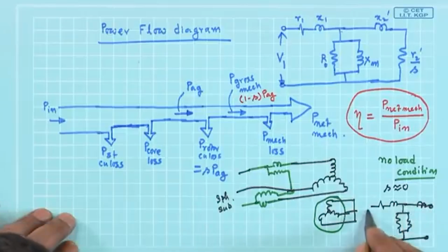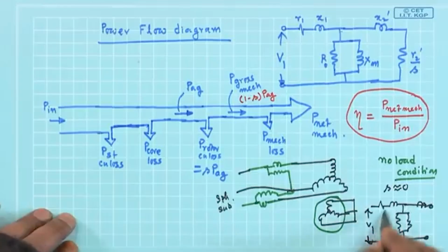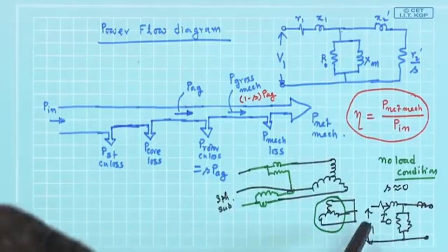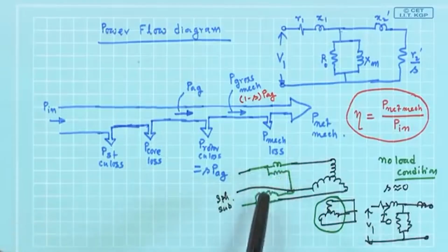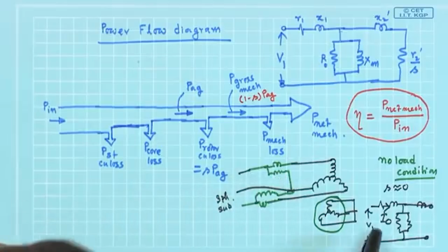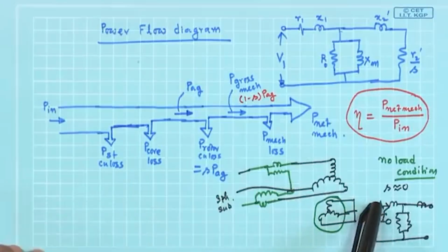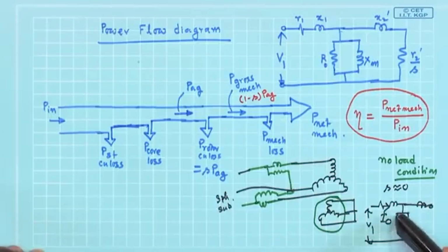So, nothing. So, V1, and this is the no load current I naught, the total current drawn. Therefore, I will say the sum of these 2 wattmeter readings must be equal to I naught square into R1, is it not? Similarly, there will be power loss in this resistance. R1 X1 is small, approximately the same voltage comes close to that.